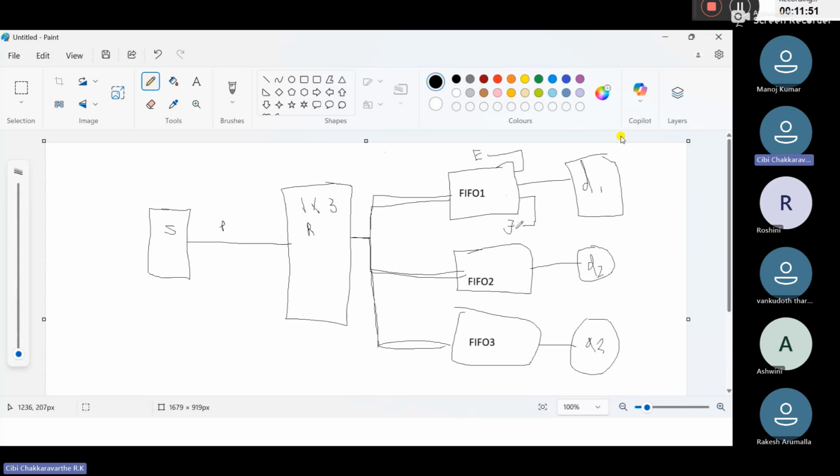That is why this FIFO is used, and this FIFO has indicators showing whether it is empty or full. If the FIFO is full, we will stop passing our data. If our FIFO is empty and we do a read operation, it is a waste of time. Am I correct? Yes, because if we have an empty storage and need to read something, what will we read? It is nothing.